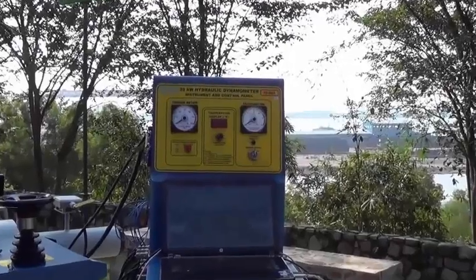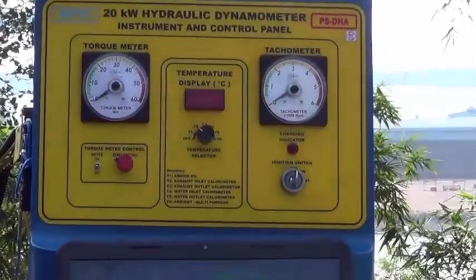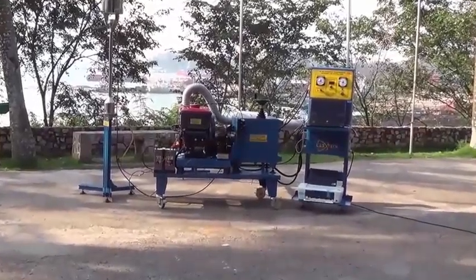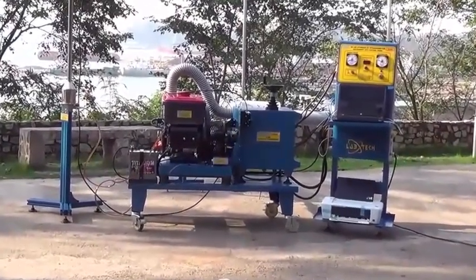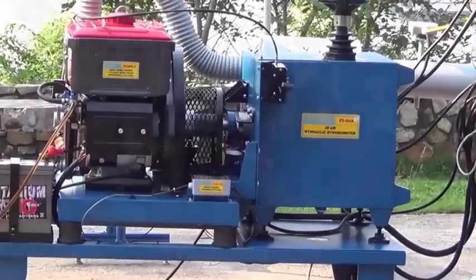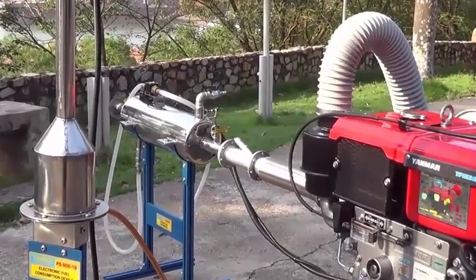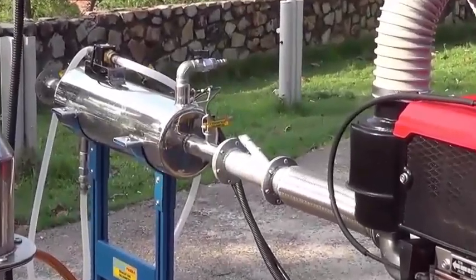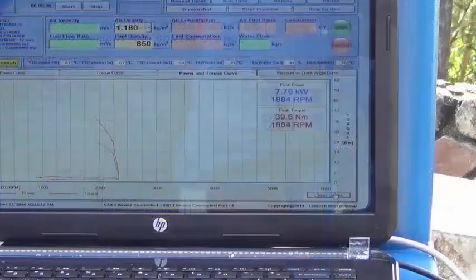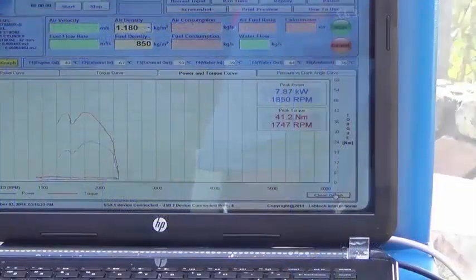Small internal combustion engines of various kinds can be fitted to the system, including 4-cycle petrol engines, 2-cycle petrol engines, kerosene engines, diesel engines, and small motorcycle engines. The dynamometer trainer is a fully self-contained hydraulic type unit enclosed in a sturdy steel base which can be used on a bench top. Engine mounting plates are provided for each type of engine supply, allowing quick setup for engine testing. Built-in precision load control can accurately vary the engine load so that torque readings may be taken at different RPMs. Torque is measured by an electronic load cell and built-in torque meter, and engine speed is monitored by an electronic tachometer. Engine power output can then easily be calculated from the torque meter and tachometer readings.